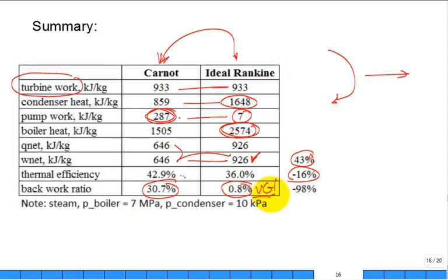Okay, let me ask you this. You learned this equation, and I told you it's going to be on the EIT exam. The probability is high in the thermodynamics section that you're going to need to use the efficiency of the heat engine, Carnot: 1 minus the low temperature over the high temperature. Simple equation, true? We learned it.